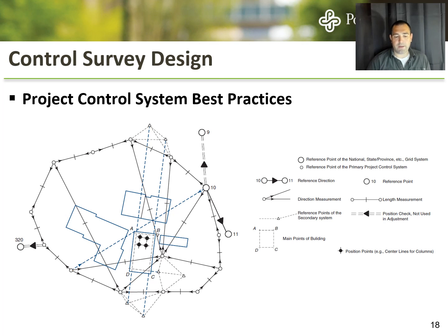When you're setting that up, you need to be pretty circumspect about what you're tying into, for a lot of different reasons. You're always going to have to tie into some sort of reference system, but you're also oftentimes going to set up your own temporary control points to allow you to quickly take those measurements without having to move your instrument to a bunch of different locations. On the left is an example: let's say that we're building a building, and we're tying into some known benchmarks. You need to tie into at least one elevation benchmark, and then at least two known points with known horizontal coordinates, in order to get your survey referenced in properly.